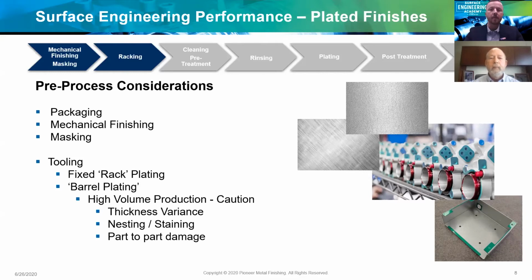But let's focus then on the surface texture, or the pre-treatment from a mechanical perspective of the substrate. And really what we have here, not a lot unlike anodize or even paint or powder, is that a very smooth or polished surface will produce a high shine result after plating. Just the same, a roughened surface, whether you're using blasting or some sort of straight line sanding or tumbling effect, or even a chemical etch, will produce a matte finish.